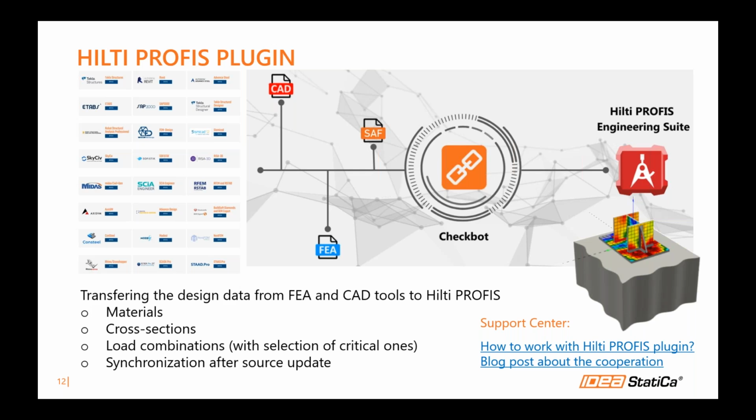And typically, if the structural engineer wants to use it, the import of load is very often made manually. You have to select the most important ones or some envelope blanket combination of loadings to put there, just not to spend too much time with tens or maybe hundreds of load combinations.